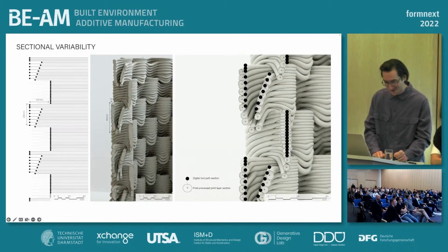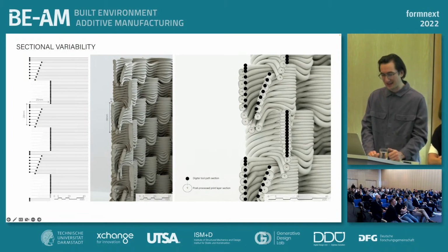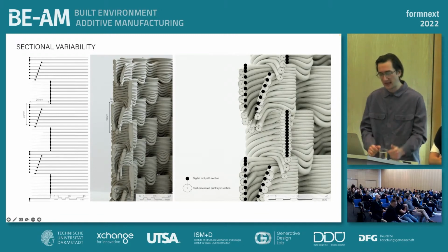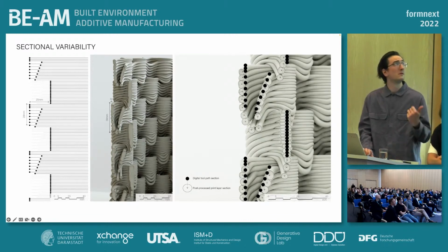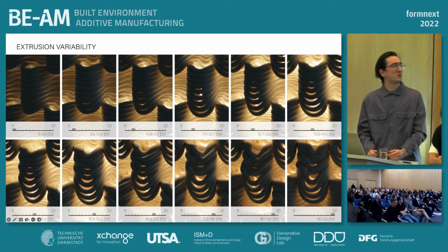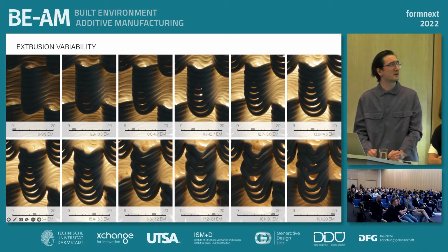Excellent. So the apertures are designed to kind of deform heavily on the exterior and kind of remain stable on the interior. And these patterns kind of overlap to create two kind of like distinct light shelves in the exterior of the geometry, providing kind of this additional room for sag. The patterns realign on the interior to kind of form a more stable internal wall there. And the relationship between kind of aperture size and brightness in this one is nonlinear. If it's too small of an aperture, you don't get enough light. Too big of an aperture, it collapses on itself, you don't get enough light either. So there's a sweet spot in the middle there that starts to grade light.